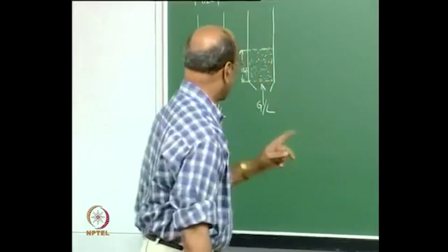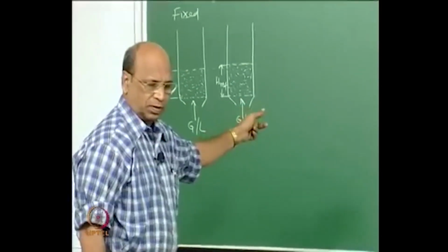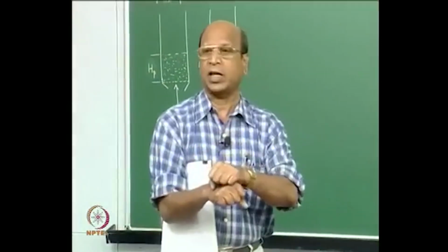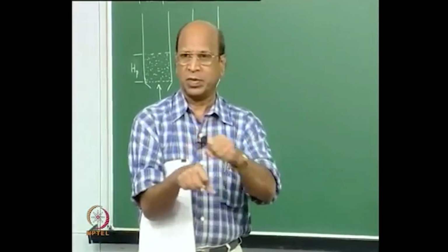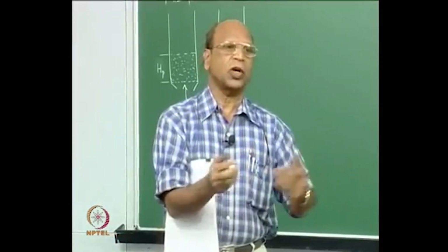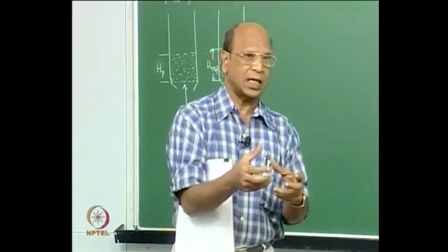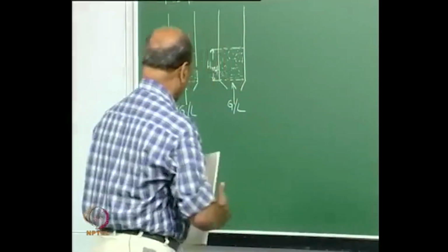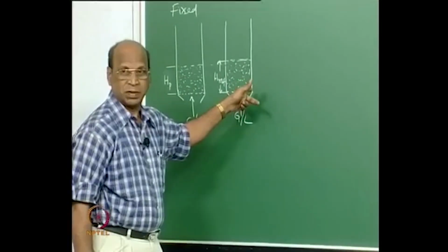So it comes out beautifully. Heat transfer is the same thing; heat is uniformly transported. On the other hand, if you look at a packed bed of the same height, what happens? In a packed bed, the particles are resting one above the other, right? That means some contact area is always lost for the solids. That contact area is not available in packed bed conditions, talking about the same particle size.